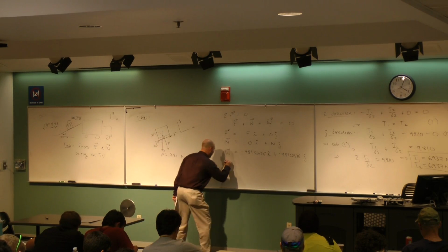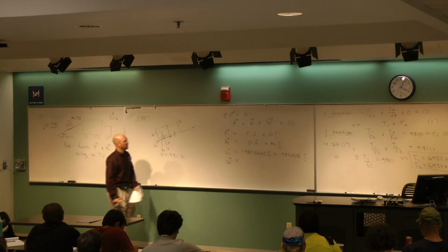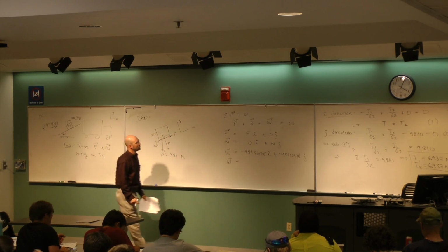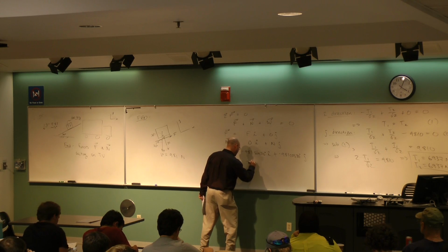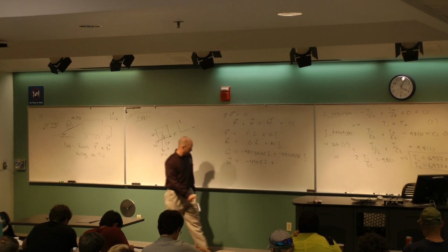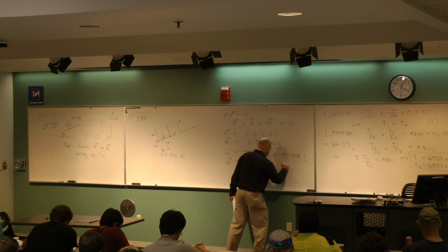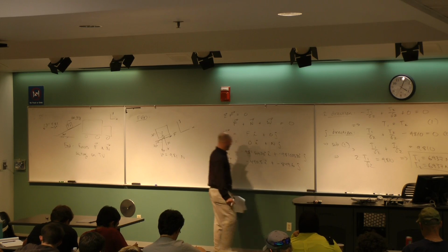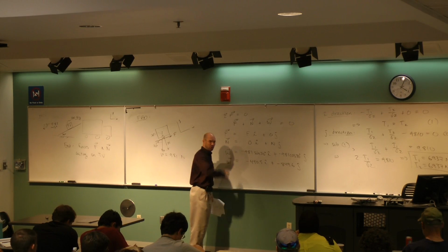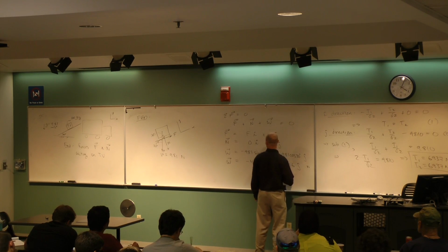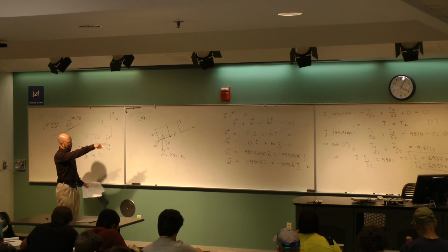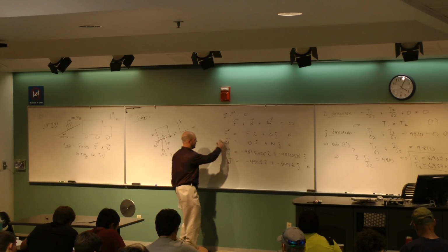Okay, and if we want, we can put numbers in. Somebody run those numbers for me on a calculator. 981 sine 30 is how much? 490.5? 490.5 i, plus cosine 30? Negative 849.6 j. Now, if I were going to box these, I'd put units on them. If this was a final answer, I'd say that's newtons, and even this one is newtons. So again, the N that I'm putting there is the unit, not the value of the unknown N.